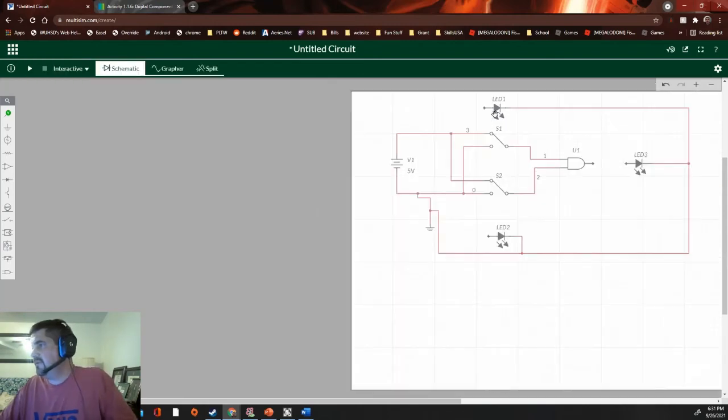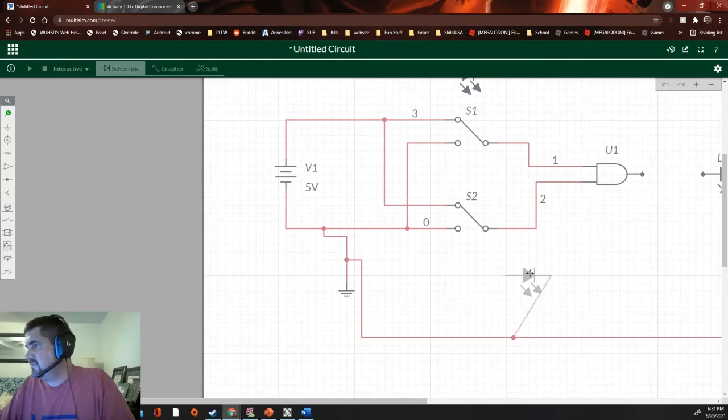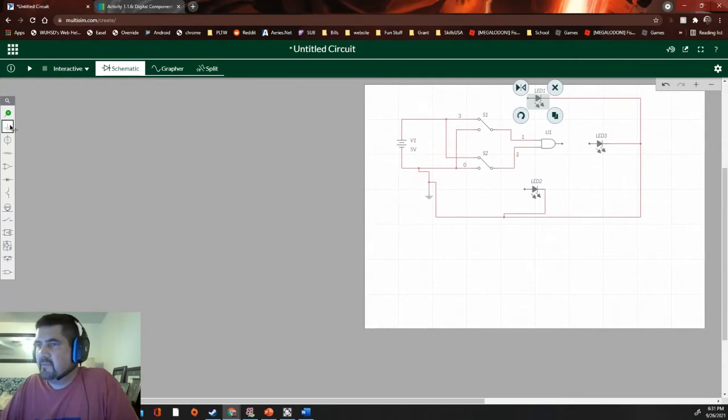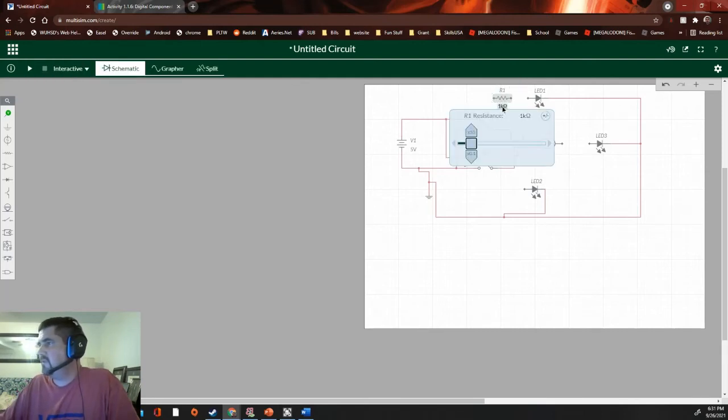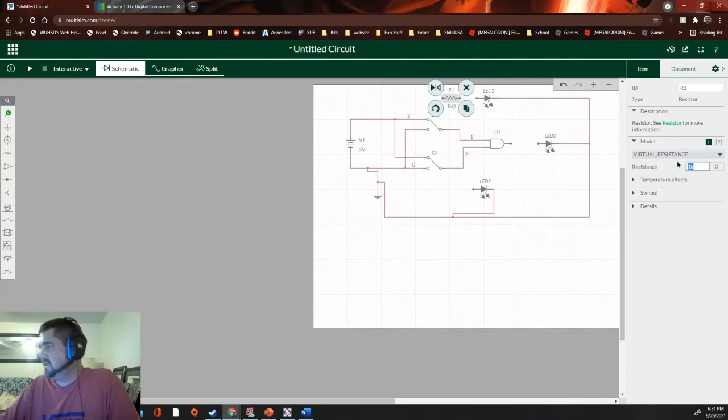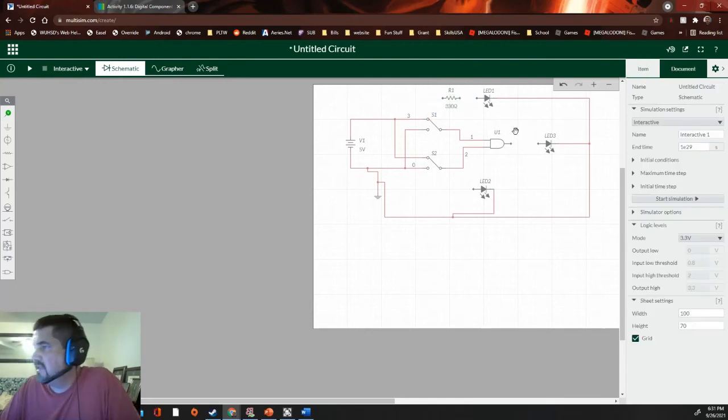Actually, I just realized that these should be a little bit more like that. There we go. So that gives me more room. So let me get my resistors, and I'm going to do one here. And I notice it's 1K. So I double click that 1K, or you can click this. And when I double click it, I can change this to 330. That's kind of the more standard here for these small LED ones.